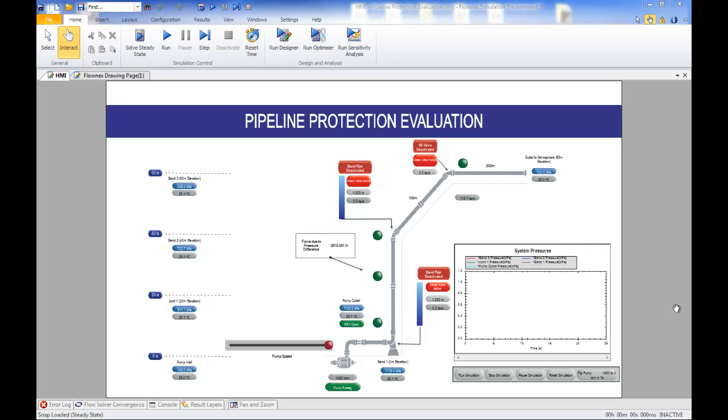The second example is of a water hammer analysis. Due to the nature of mine water reticulation systems, they are susceptible to pressure surges. In this example, we are pumping water to an elevation of 60 meters, and we are interested in investigating the pressure surge at bend locations due to the pump tripping.